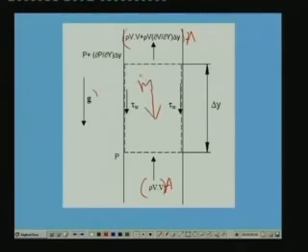Let us say that this is due to the mass of the fluid in the control volume. This is one force, and you also have force due to shear stress at the wall of the capillary tube. This also acts in the opposite direction. It tries to retard the flow of refrigerant. So this also acts in the downward direction, and the pressure acts at the inlet of the control volume in this direction, and at the outlet the pressure acts in this direction.